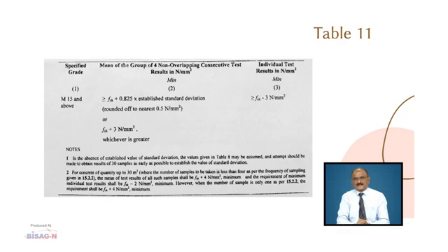The individual test results in Newton per millimeter square given here is the value of one sample of 3 cubes. So, each of these samples which I have shown, 1, 2, 3, 4 samples, each of that should be at least more than FCK minus 3 and average should be FCK plus 3 or FCK plus 0.825s. Yes, that is what is required. Where number of samples are less than 4, then instead of FCK plus 3, it should be FCK plus 4. That is the minimum required.